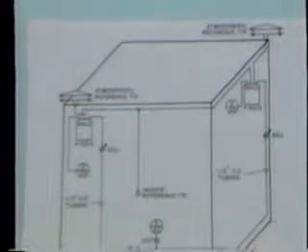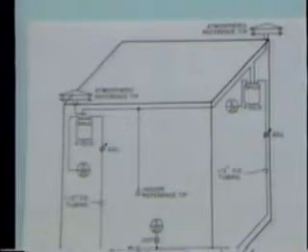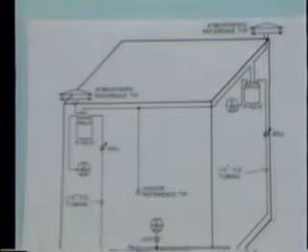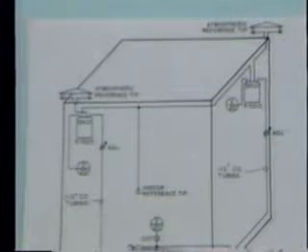Each year, more experience is gained. More work is done to study pressure patterns around the building exterior, and more successful installations continue to operate. Shown here is the latest successful attempts at obtaining stable atmospheric references. The method for the pressure sensing is basic. The flow and pressure patterns indicate a near atmospheric pressure at the building's edge on the windward side. Selecting two opposite corners assures one pickup in a most ideal location.